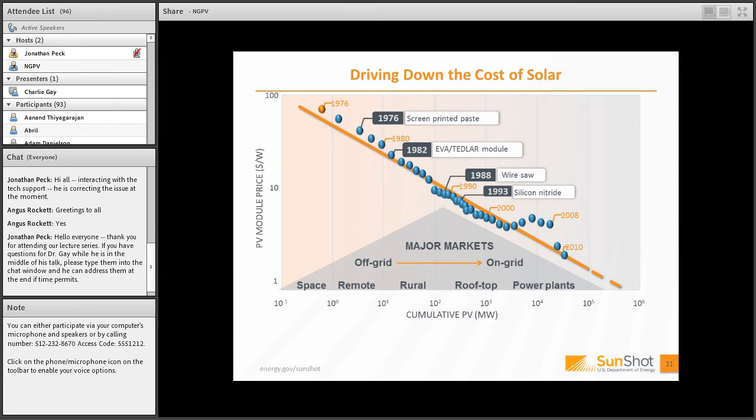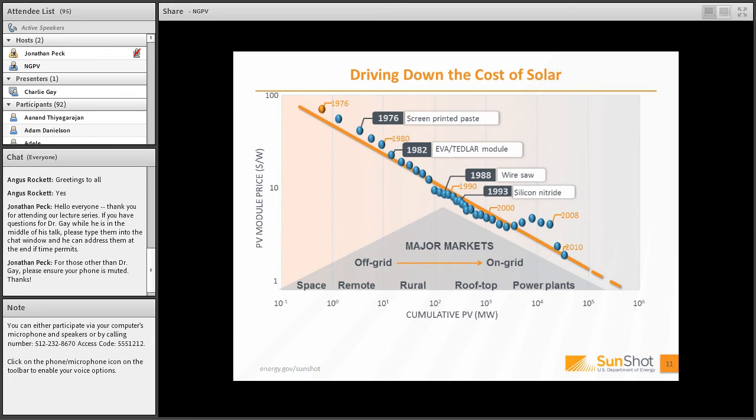So Kyocera Solar, SolarX, that ultimately became BP Solar, made big strides in efficiency because of the benefits of hydrogen migrating along grain boundaries or through bulk silicon to help passivate impurities and defects within silicon.